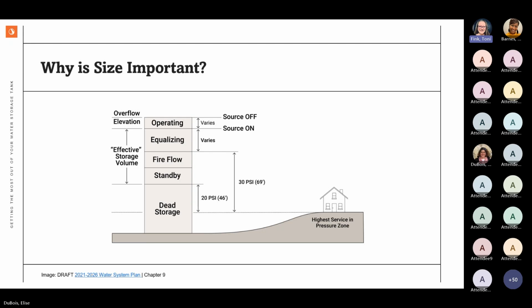What do you look for in a good inspection report? What makes it complete? Oh, these are fun. So first, we want something that looks at the structural. We want it to look at the steel. We want it to look at the concrete. We really want it to tell us what's going on with the actual physical structure, not even looking at appurtenances, just the steel or the concrete. That's the first thing. The next thing, we want to know what these experts' idea is to replace them. We want them to look at the coatings. We want them to test coatings.